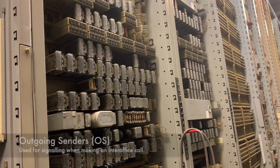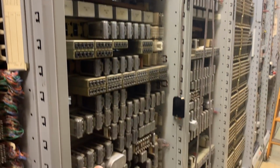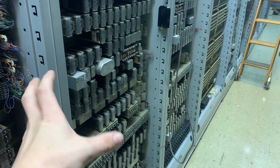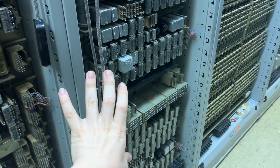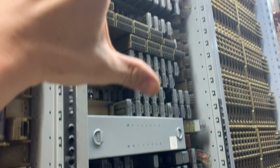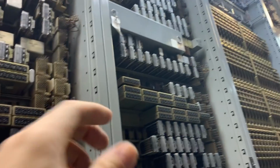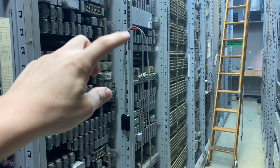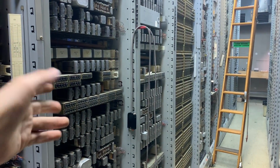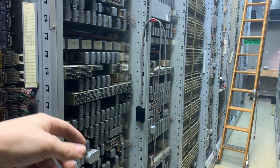So these are MF outgoing senders, used when we're making a call to an office that wants MF input. These here are dial pulse out senders when we're making a call to a step office. And up here, these are revertive pulse out senders for making calls to panel offices. Now these out senders are only used when we're making inter-office calls. So one will come around eventually, but I just don't know when because it's random.